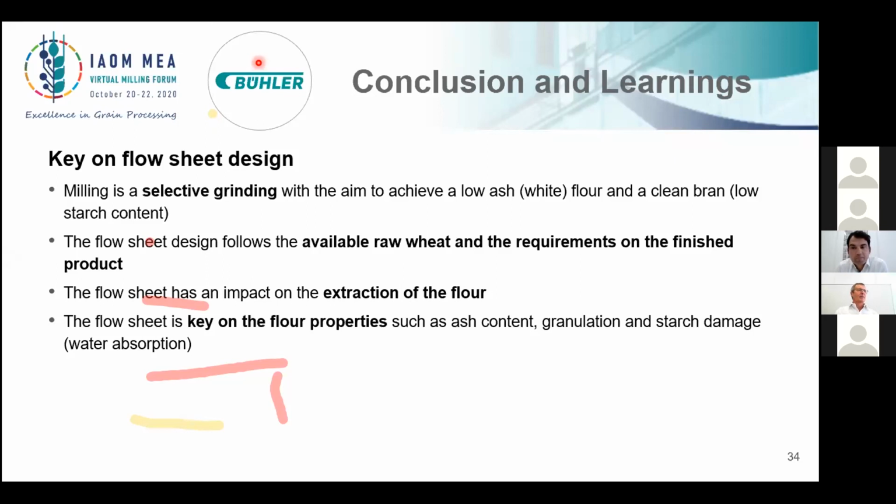Moisture in wheat germ. The wheat is conditioned, and the bran and the germ take the water. If conditioning starts with the tempering time, the water penetrates. So as we go through the milling process, the bran and the germ are losing moisture. Yesterday there was also a question, what is the moisture of the bran? My experience is it is even lower than the flour. And the same for the germ.